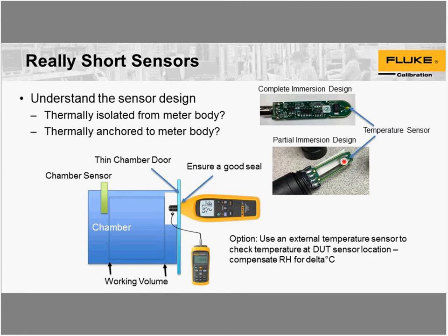I've looked at other sensor designs where the temperature sensor is really on wires, very thin wire, to help isolate it. And then, of course, the humidity sensor: the interesting thing is it doesn't have a thermal gradient sensitivity. The humidity sensor just has to be in the area that you want to measure, so it isn't so sensitive. Up here on the Duke sensor, here's the humidity sensor. It's an IC type integrated circuit humidity sensor.